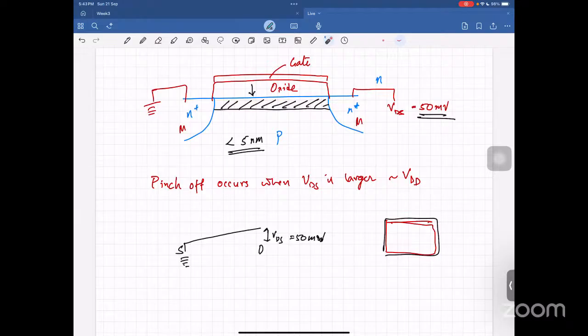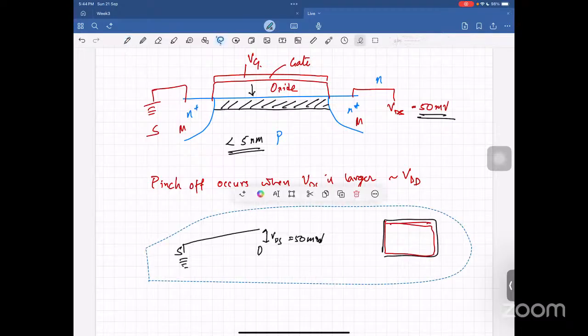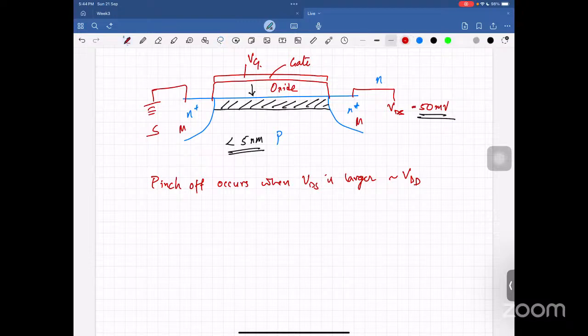So now essentially what you have is your gate voltage, VGS, VG, and then the source voltage. You can think of this entire region of the gate as a series of capacitors. Let me try to put that here. So this is my oxide. Think of a series of tiny capacitors like this. They're all in parallel, so it's just one large capacitor.